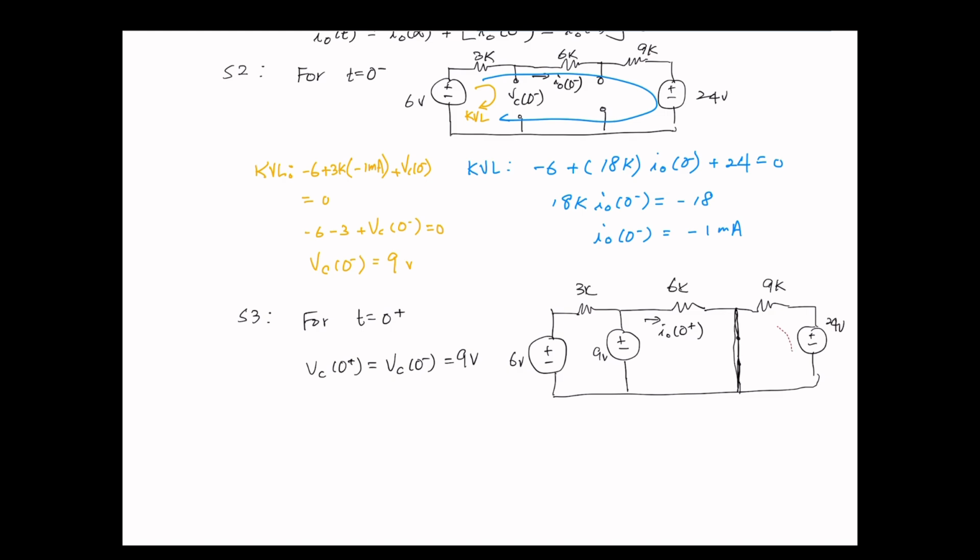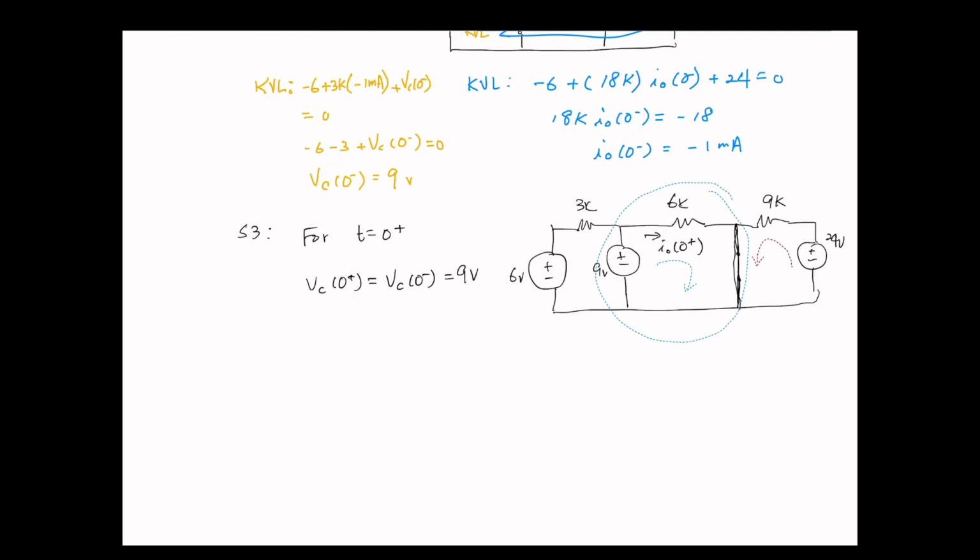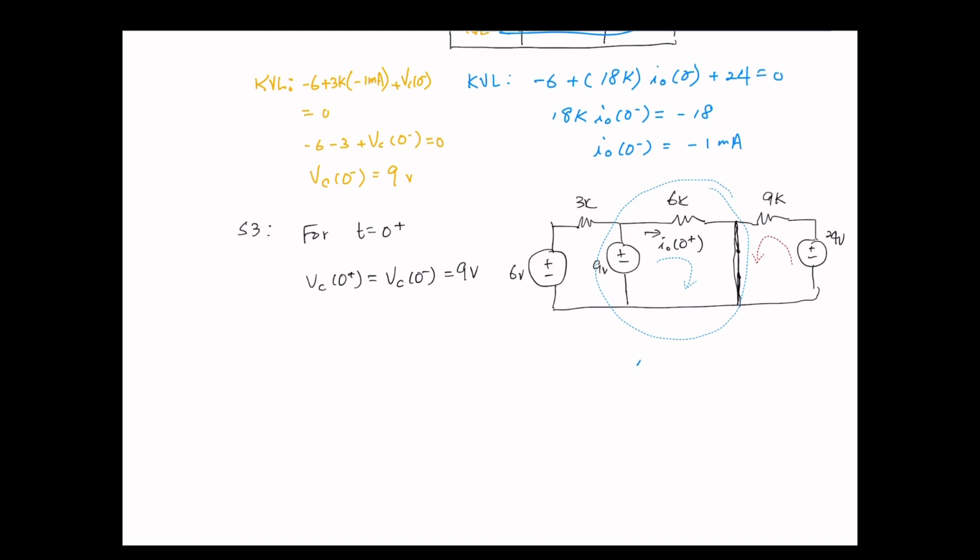The left side of the circuit is going to go in that, and the right side of the circuit is going to go in that. Therefore, looking at this portion of the circuit, we have 9 volts and one resistor 6K right there and nothing else. Therefore, I sub 0, 0 plus is V over R, 9 over 6K, and that is 3 over 2 milliamp. Hey, Dr. Kim, what happened to the left side or right hand side?